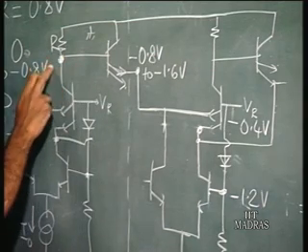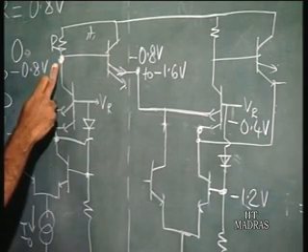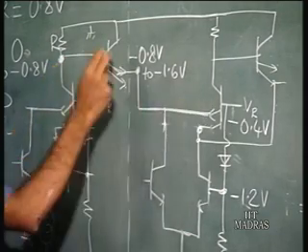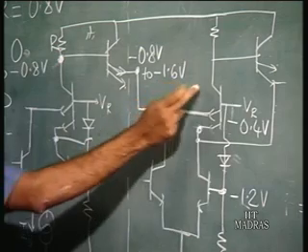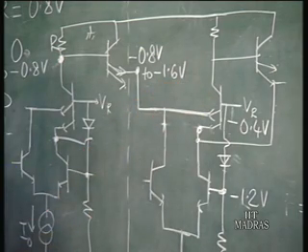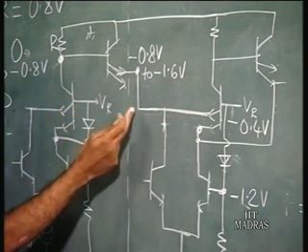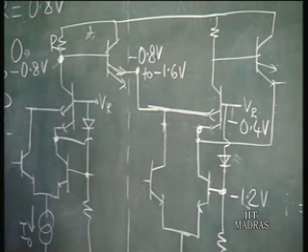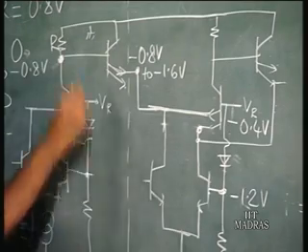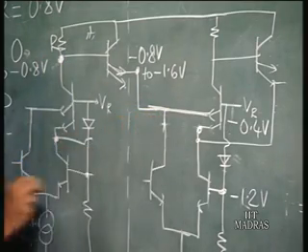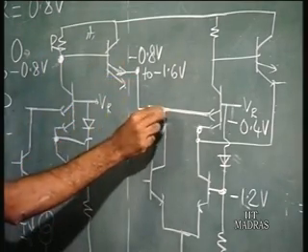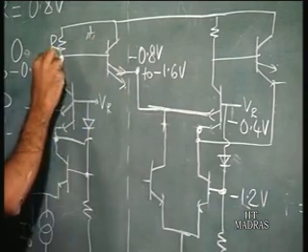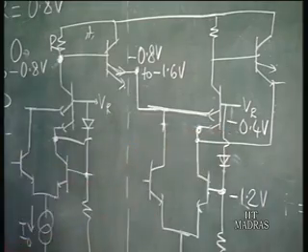So, if this voltage here you see is 0 volts, what happens? This transistor is on and this transistor is off. So, that is what we have said. If the input is high, we have said already that this transistor is off. So, between these there is perfect voltage compatibility. You can feed this output directly as a direct input here without any level shifting necessary, because this voltage varies about the reference voltage here.